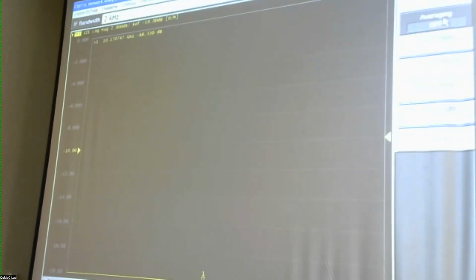And for that, it lists all the possible scattering parameters which this instrument can measure, because it has 4 ports. So it's giving you all the combinations from S11 to S42. Currently it's set at S21, which means it's measuring the scattering parameter going into port 2 from port 1. So remember that the first index is the destination port, and the second index is the source port. That's the convention that is used.